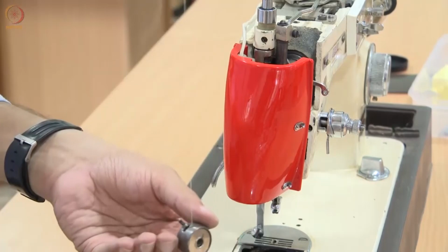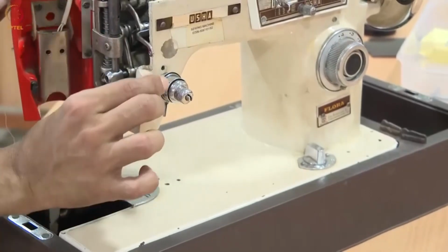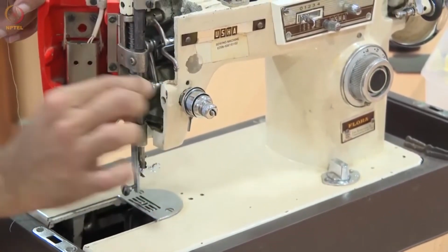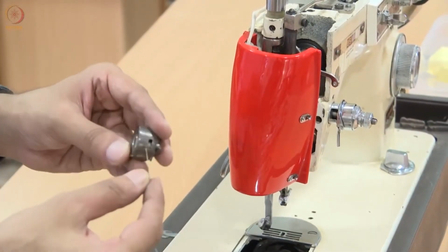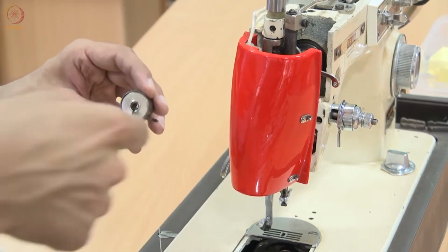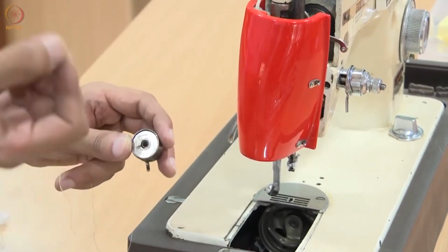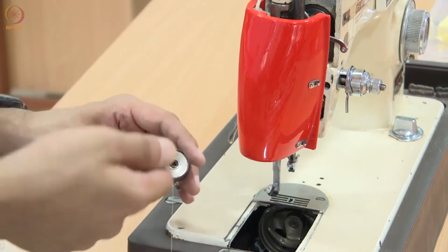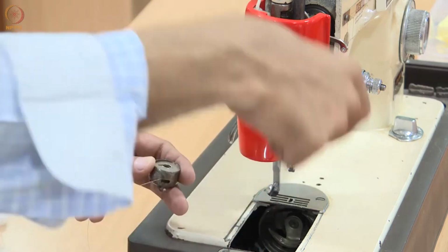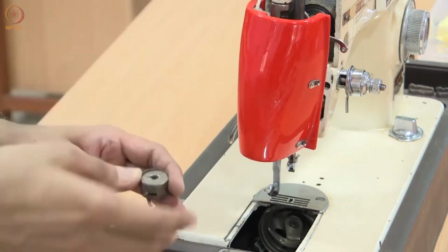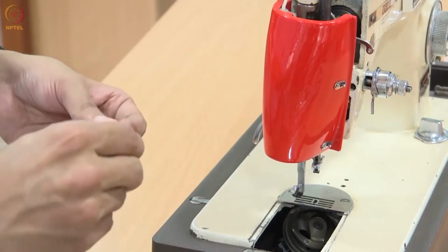Now even if I let it hang, it won't come out, because this spring puts a certain amount of pressure on the thread. There is a certain preset amount of tension that the spring exerts as a force, and that controls it, because remember, the top part of the thread pulls this thread. So there has to be some resistance, right? There has to be just enough resistance such that all of the spool does not unwind at once, but unwinds just enough to feed the little bit of thread needed to perform that part of the stitching. So this gives you a frictional torque. We call this frictional torque.